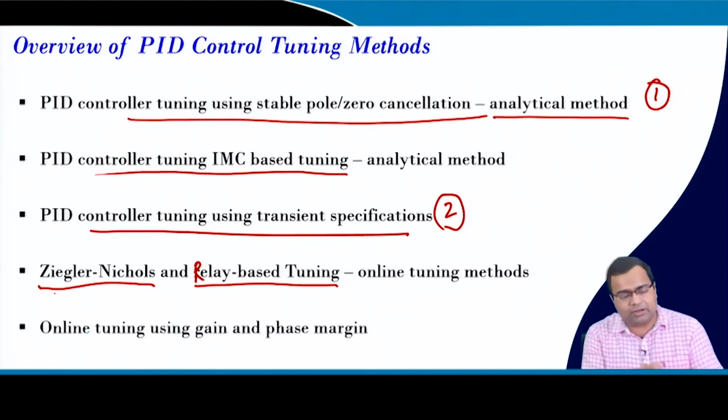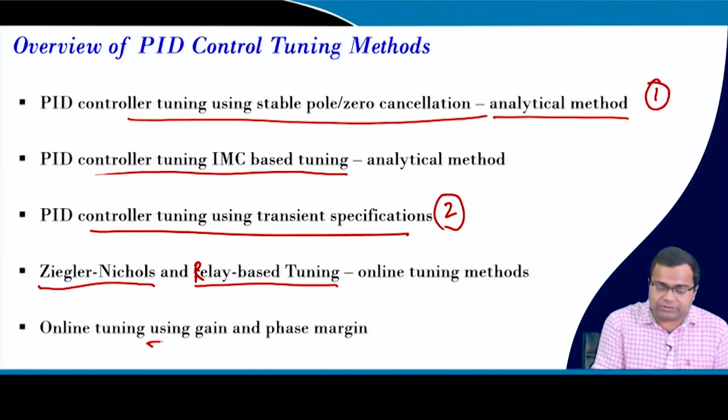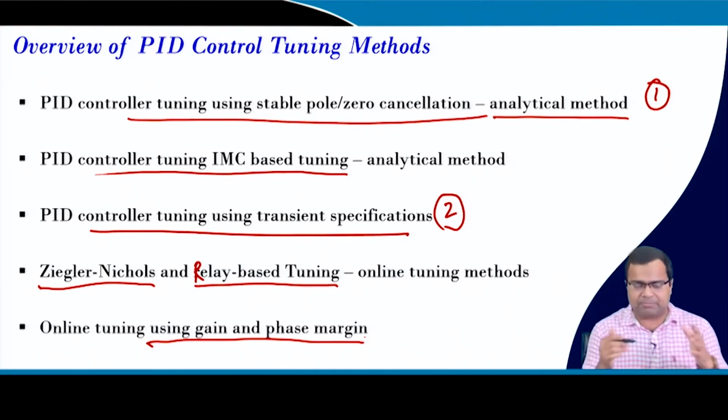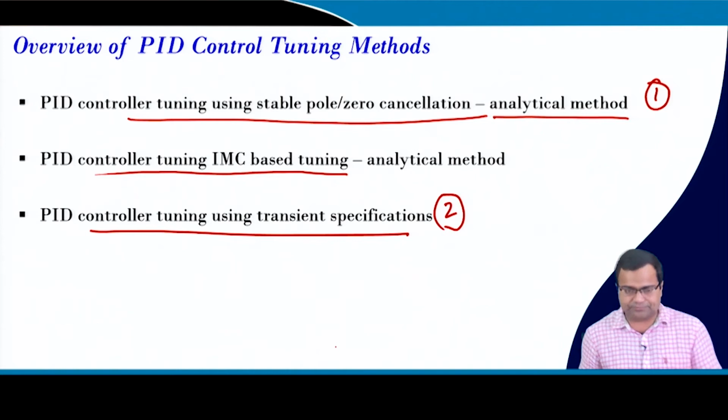Then there are other methods of tuning, online tuning using the frequency response method, where if you set the desired gain margin and phase margin, you can actually tune the parameters. Okay. So, this is also an online tuning method, and there are multiple papers, because we are not talking about digital control, multiple pioneering works have already been proposed in this context.